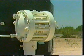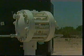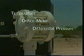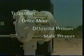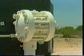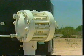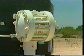For instance, to determine the volume of NGLs with an orifice meter, the temperature, orifice meter differential pressure, and static pressure or static constant must be known. The orifice meter station creates a differential pressure and records the differential pressure and sometimes the static pressure. For a more detailed discussion on orifice meter stations, review the tape on orifice meter station fundamentals.